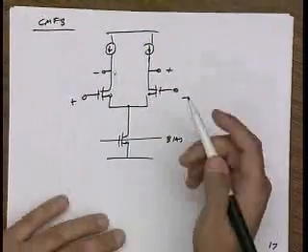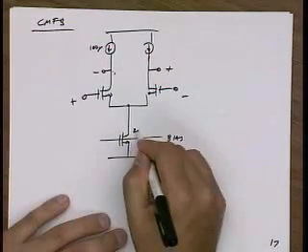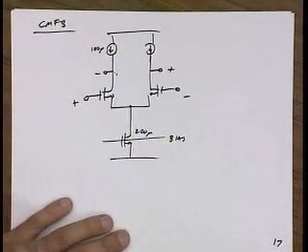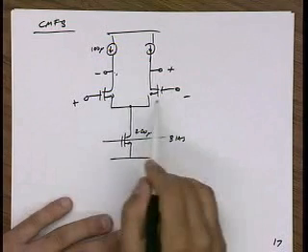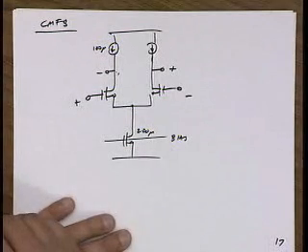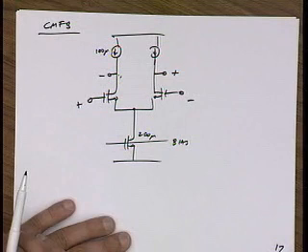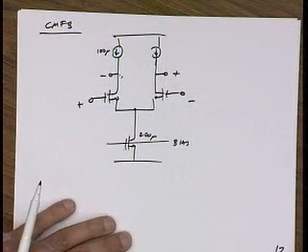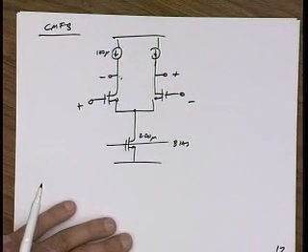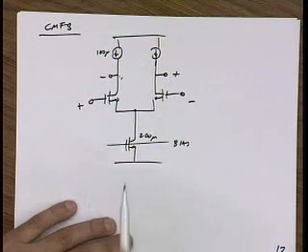Let's say I'm designing this, and let's just say this is 100 microamps, and I bias this up to be 200 microamps. So if the differential input is 0, differential output is 0 too, right? Circuit should work. So why introduce another feedback loop if you don't have to? Because of like mismatch? Yeah, exactly.